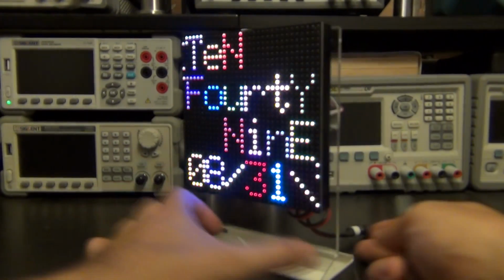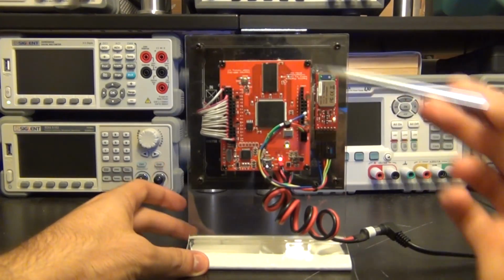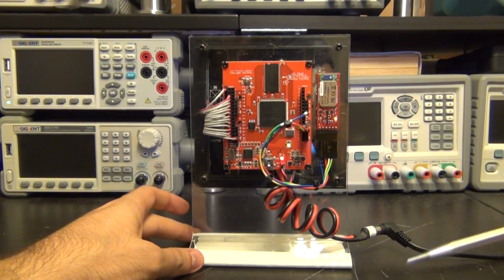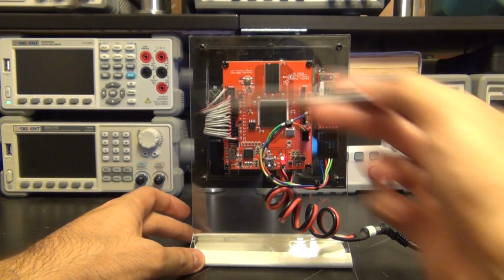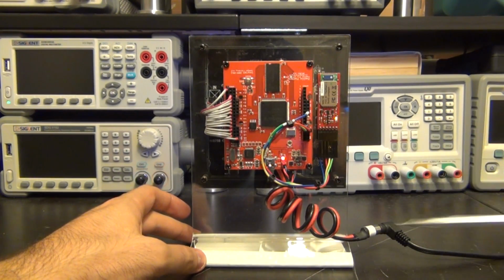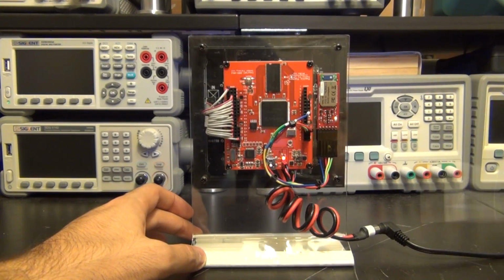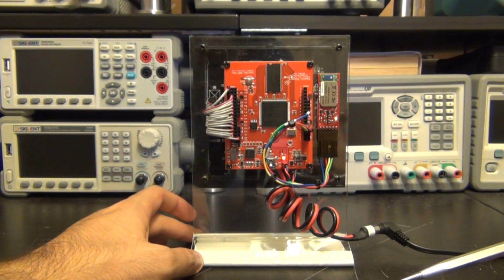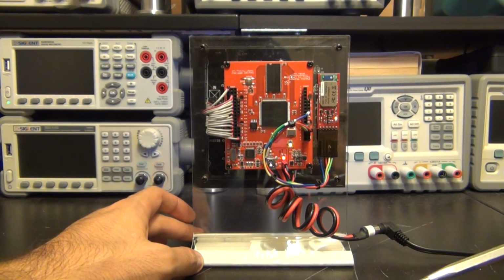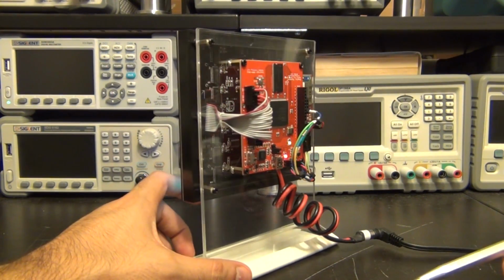And if I go ahead and turn this around, you can see that we have our FPGA board, our Bluetooth RS-232 interface over there, and the display driver coming from the FPGA board, and all it needs is power. Everything else is handled through the Bluetooth interface. So this is in a way like a video card that receives a frame of information, and then it buffers it and then displays it continuously in the background. And of course the FPGA handles all of that.